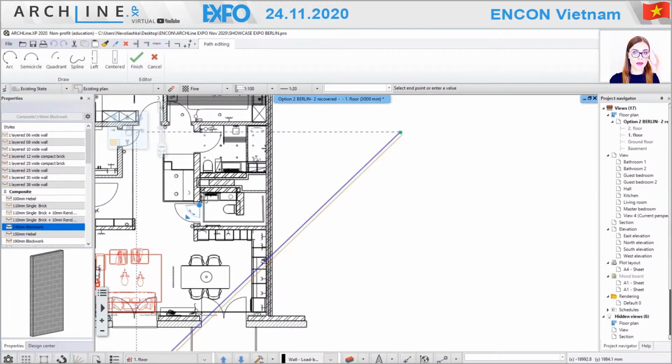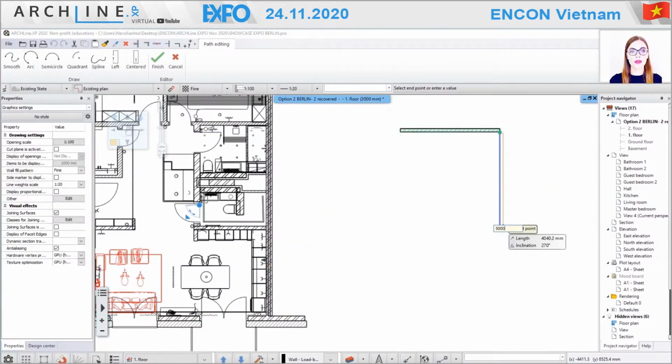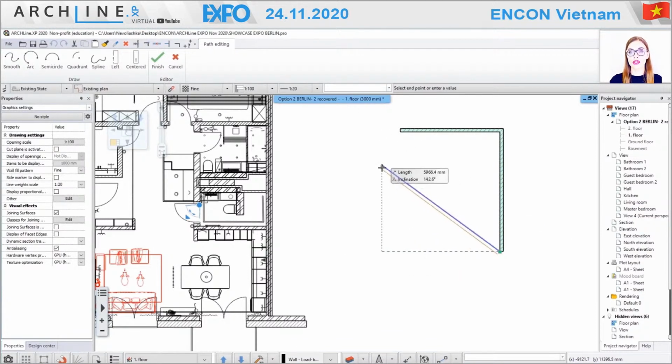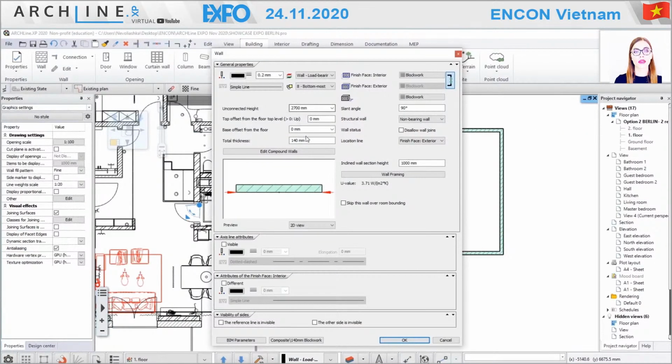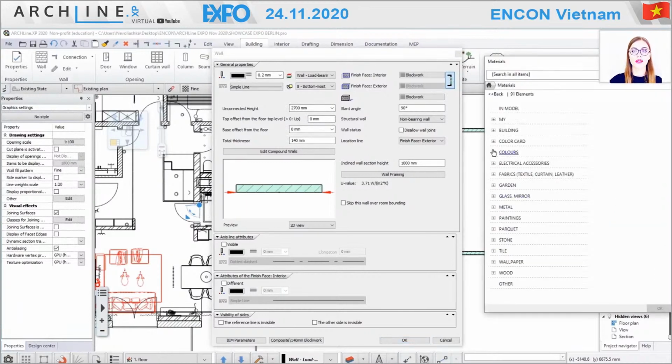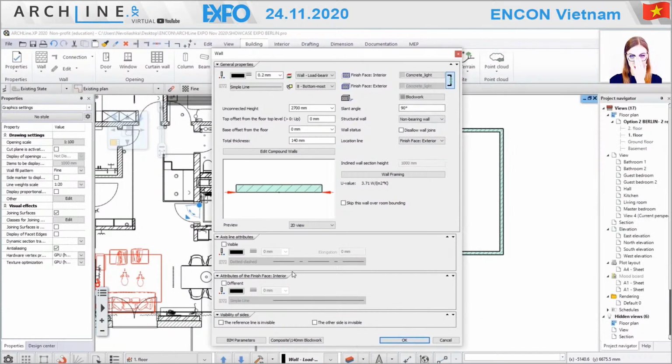So you see that, for example, now we create the walls, and you can choose options and create a spline or just follow up with a rectangular shape, which is what I'm actually doing. And then you can go on and correct your wall if you're not satisfied with this. It's very easy to do, even on the level of interior design, creating the material you need, or you also can think about documentation, how you will represent it. For example, the outlining or a hatch.